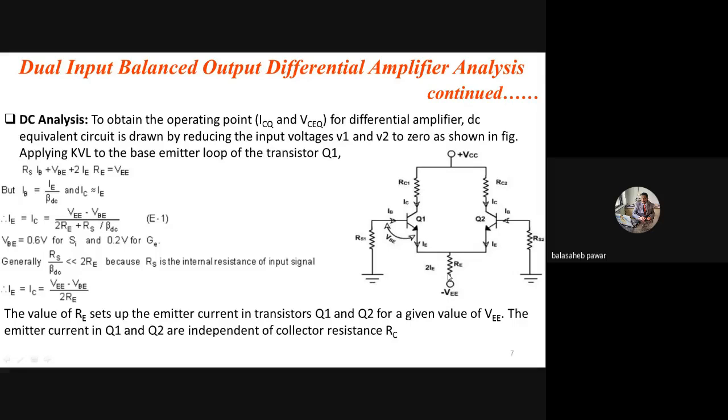So it will act as an amplifier when it is biased in its amplifier region, and that biasing is done using minus VEE and plus VCC and this biasing component, resistor RE. There is no voltage divider bias, no self bias, no feedback bias.